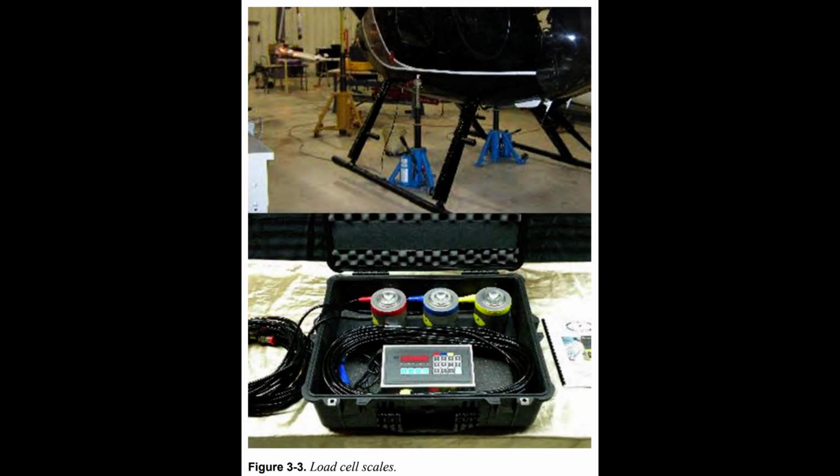Jacking an aircraft off the ground from all load points can be an inconvenience, as well as a safety risk, which some operators would rather avoid by opting for more expensive, but simpler to use, platform equipment. In addition, weighing with platform scales typically takes only 1/3 of the time needed to weigh with load cells. End of page 3-2.